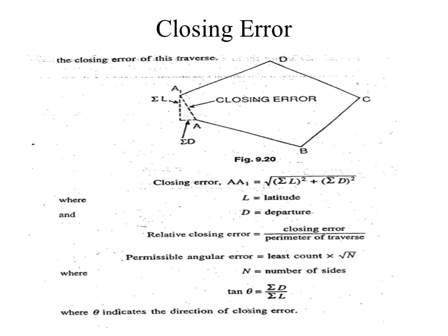In this method, bearing of line is taken. After this, the included angles of the traverse are measured. This angle may be interior or exterior. Please refer the figure 9.16. The theodolite is set up at station A. The plate bubble is leveled. Vernier A is set to 0 degree and vernier B is set to 180 degree. And then the upper clamp is fixed. The telescope is oriented along the north line with the help of tubular compass fitted to the A-frame of the instrument. Then the magnetic bearing of line AB is measured.